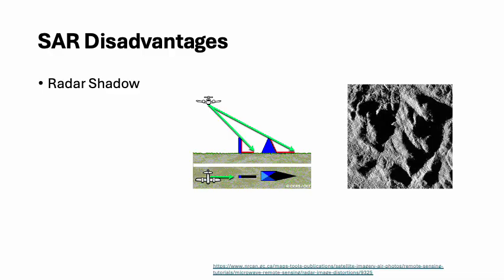As incidence angle increases from near to far range, so will shadow effects, as the radar beam looks more and more obliquely at the surface. The image shown illustrates radar shadow effects on the right side of the hillside, which are being eliminated from the left.